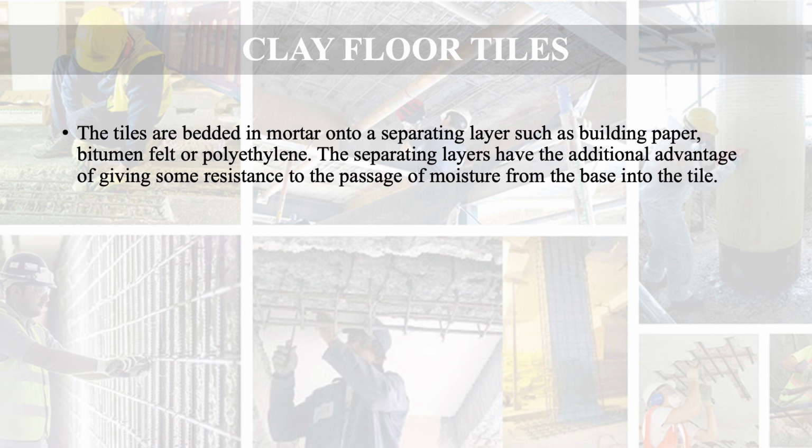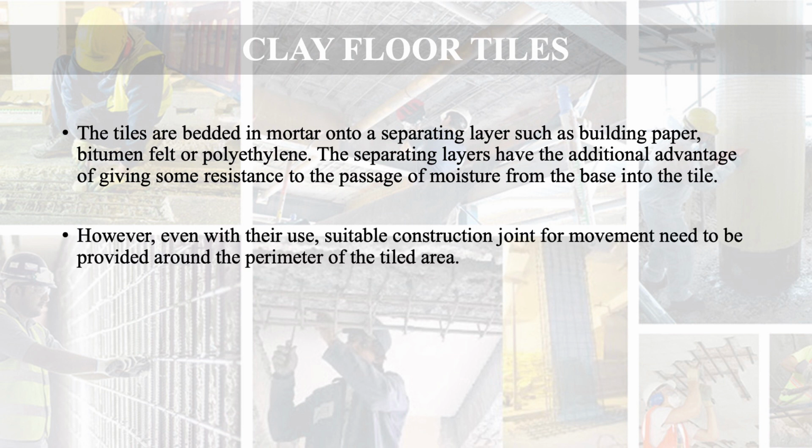The separating layer has the additional advantage of giving some resistance to the passage of moisture from the base into the tile. However, even with their use, suitable construction joints for movement need to be provided around the perimeter of the tiled area.